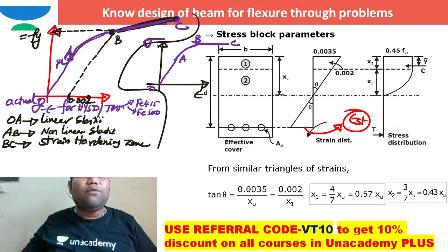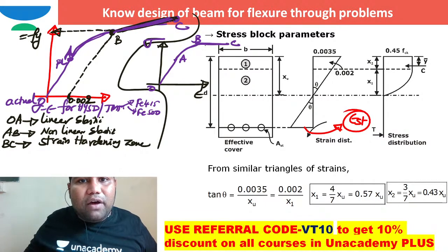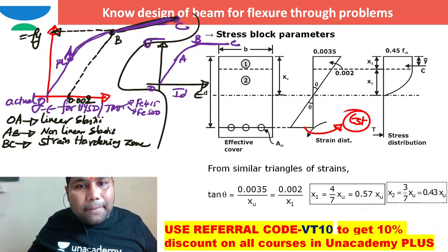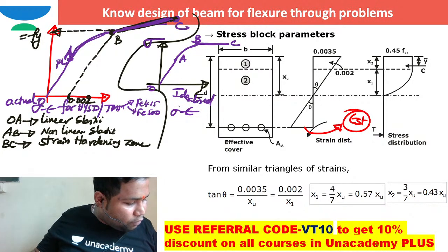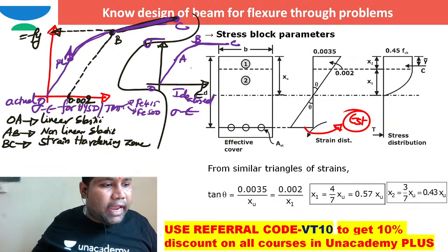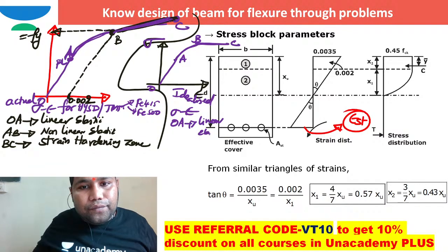This is the curve I will use. I will neglect the strain hardening zone. Instead of going upward, I am taking it as a straight line portion. This is the idealized stress strain curve, right? We make use of proof strain. Yes, we will make use of proof strain. And here, what is OA? OA in this idealized stress strain curve is linear elastic, no doubt. And AB is non-linear elastic, no doubt.